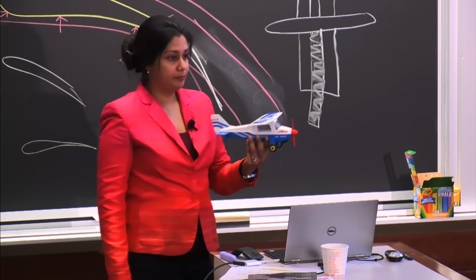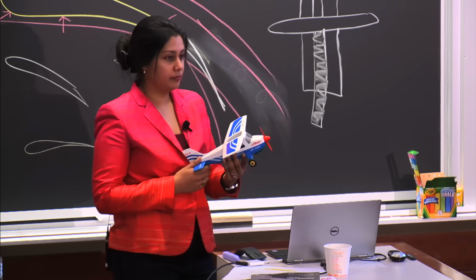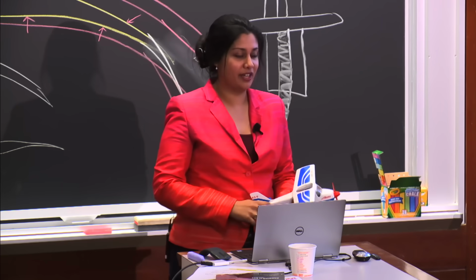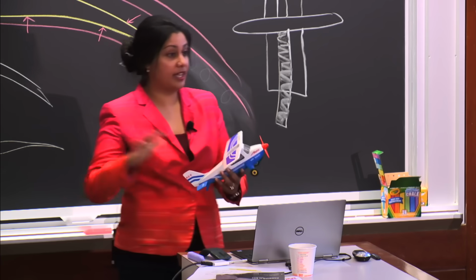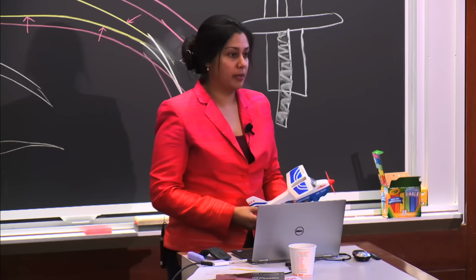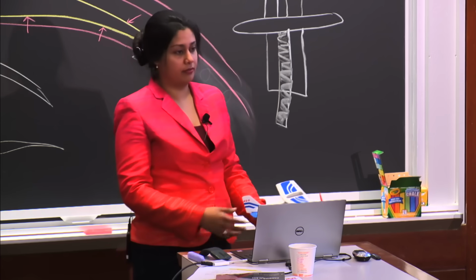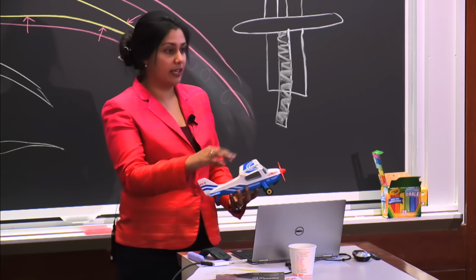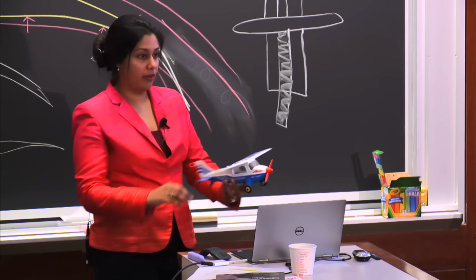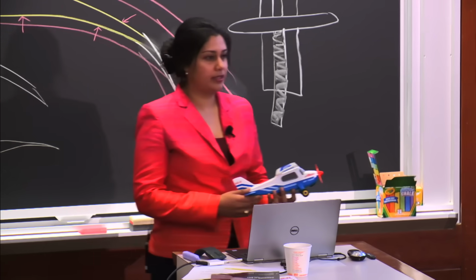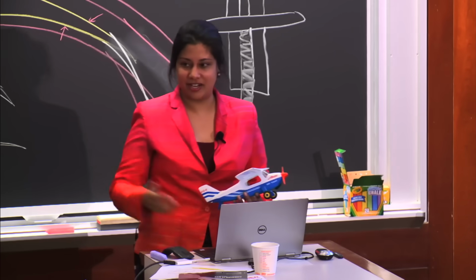So it is not 90 degrees ahead because of precession? Precession is separate. It is generating its own factors and dynamics. Both of these things are acting at the same time. Precession does, in fact, affect pitch, just like you correctly recognized. But this is an additional factor: since the center of thrust has moved to the right, it's causing the yawing. Did that answer your question? No, but that's okay. Do you want to chime in, Philip?